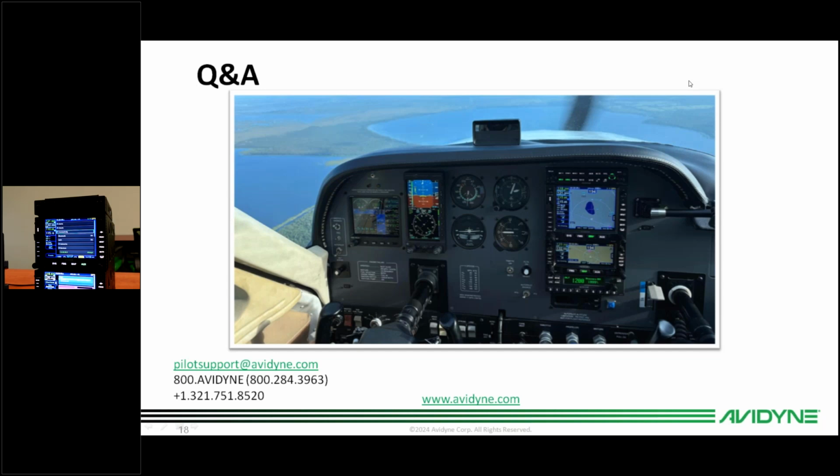Now, let's say, like the aircraft in the picture here, we have a Skytrax 200 ADS-B in receiver installed. If I wanted to bring my Stratus on board and use ForeFlight, it wouldn't matter whether it's in ForeFlight mode or not. It would just treat it like an extended GDL90 device, like a Sentry or something else. So the IFD is keeping its own traffic and weather and is happy with it, and my iPad is receiving traffic and weather from the Stratus.